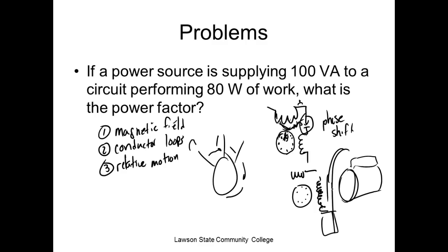So you can make it start manually. If you manually start it with your hands, and it comes up and runs, but the problem is it'll run in whatever direction you spin it in. Which may or may not be good. Some motors you don't want to run backwards.